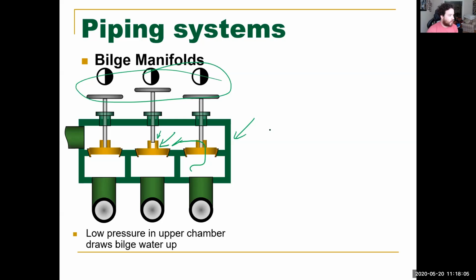Wilden pumps are self-priming, and they're going to be drawing a fluid, and air is a fluid. That fluid is going to be constantly coming into here, and you're not going to really prime your pump. You're going to be getting like 1/3 of the volume, and it's going to take 3 times the amount of time to pump that one bilge well. All right. So good habit as always: just close them if you're not using it.